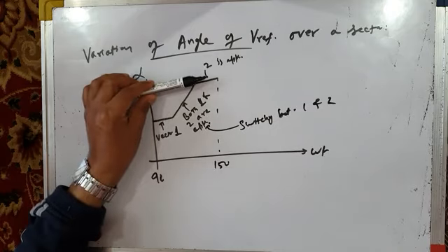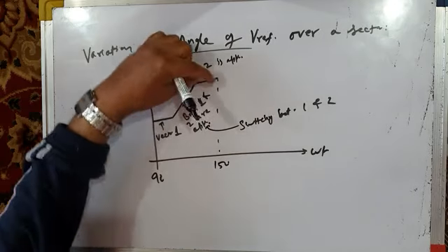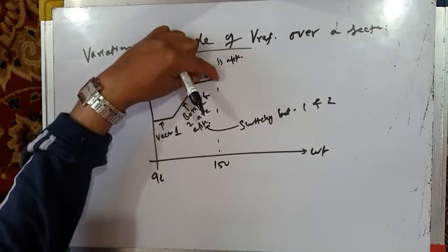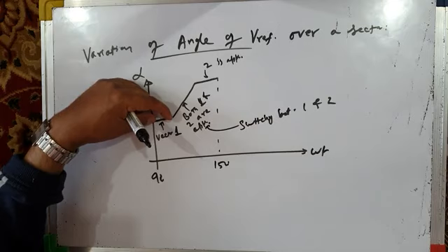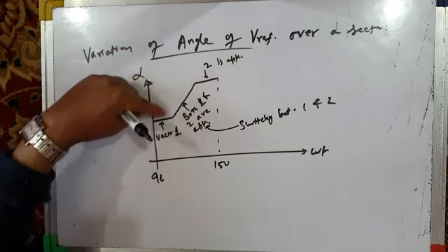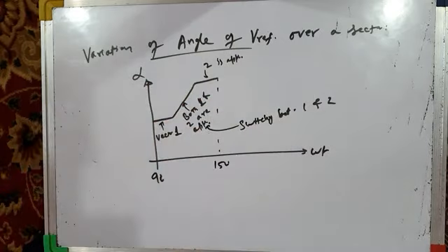And when it reaches 2, it remains at 2 for fairly long time. So here, when it is at 2, it remains there for some time, and during that period angle does not change. And similarly, when it starts from active vector 1, it remains there for some time, angle does not change. And in between, angle changes linearly, because during this period both active vectors 1 and 2 are applied.